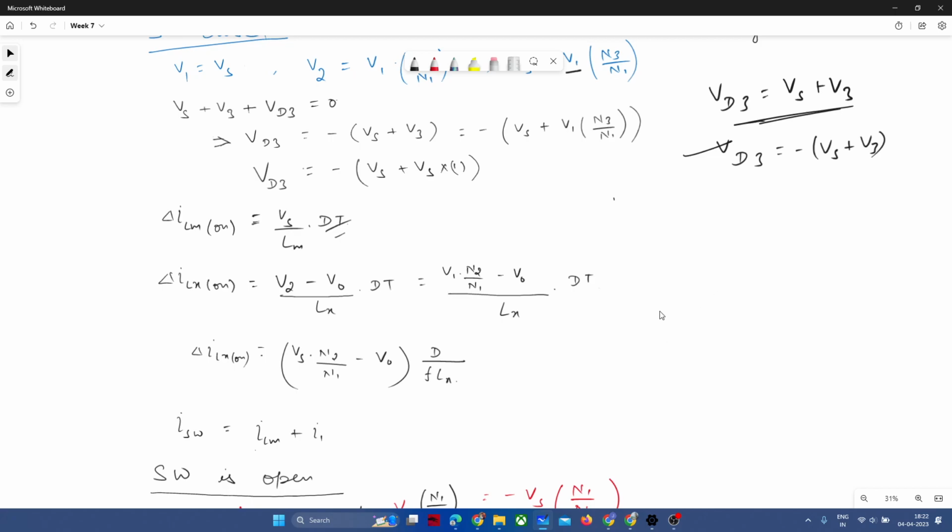And if you want a certain kind of magnetomotive force, the expression of MMF, what can be generated, is N into I. So it is up to you how much MMF you want and by which parameter. If you have a limited constraint on current, then you can increase the number of turns and get the desirable MMF. Otherwise, you can increase the current with a lesser number of turns, right? So it's up to you.